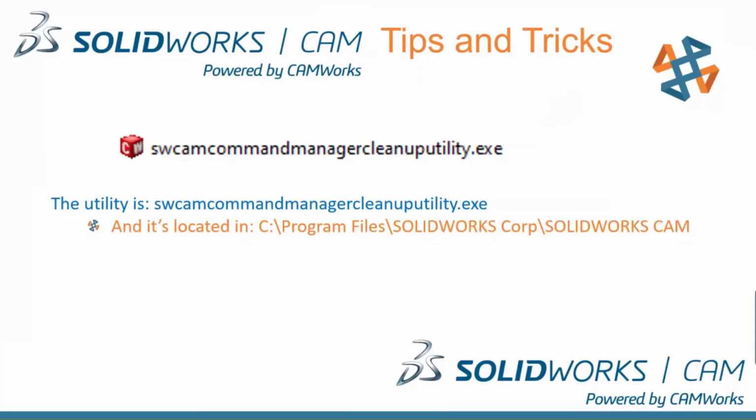So sometimes your utility manager, which is your command manager, can have some buttons show up missing. There is a little utility executable that you can run, located where I'm showing you right here, and it will reset your buttons if you ever run into that. If you look in this location that you see in orange, double click on the executable and it will run that cleanup utility.